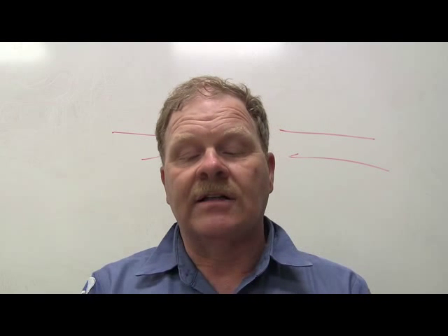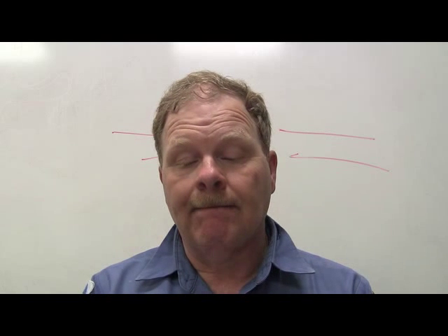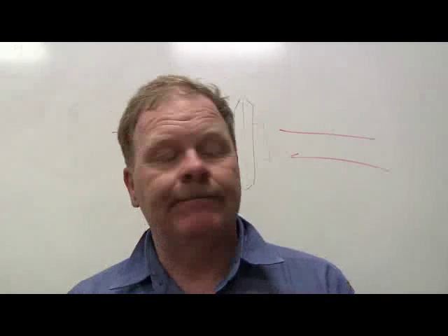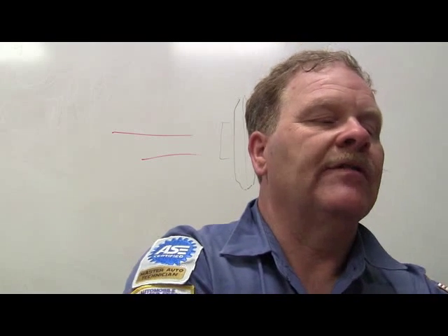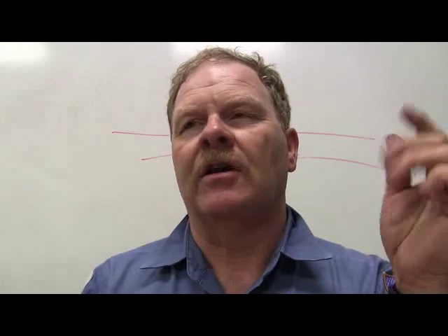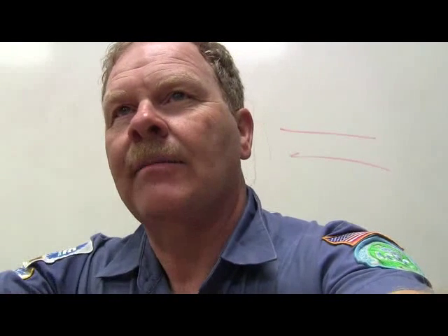A compressor clutch that cycles on and off rapidly is an indication of what? You guys have seen that before. Low refrigerant charge. Why would you see that if they have low refrigerant? Because of the low pressure switch. Whenever the low side pressure goes low, it opens the compressor circuit. You can watch it. If you watch that gauge, it'll go down to like 24 psi, and it'll come back up and go down, come back up. Short cycling is what they call that.